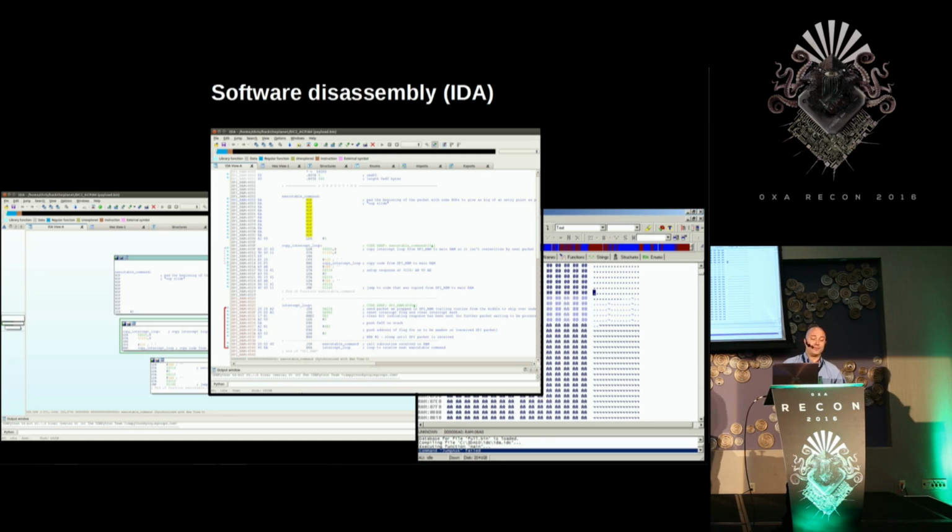Later, I remembered looking at an older access controller from the same manufacturer, which was used in a previous system, VideoCypher 2+. It's an ancestor of DigiCypher. On this older chip, there was actually a copyright notice from WDC, who licenses the 6502 core IP, visible directly on the chip die under microscope. So this would have been a good clue to the CPU architecture if I'd actually noticed it earlier. For the disassembly, I used IDA. It includes support for 6502. It's very powerful.